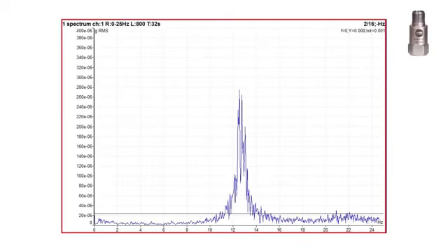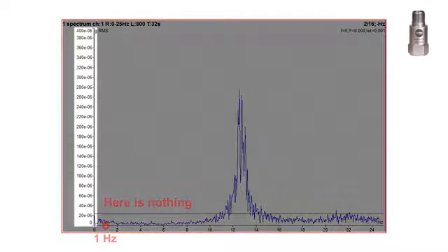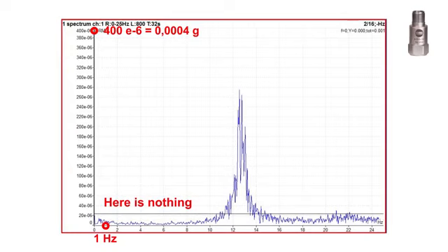On this picture I measured the spectrum in 25 Hz range only. The repeating frequency of shocks is around 1 Hz. You see nothing on 1 Hz. And again, notice the very low acceleration level. The shocks do not contain energy. If I want to see the repeating frequencies in the spectrum, then I must apply demodulation. It means I must add the energy. The demodulated spectrum can display something visible.